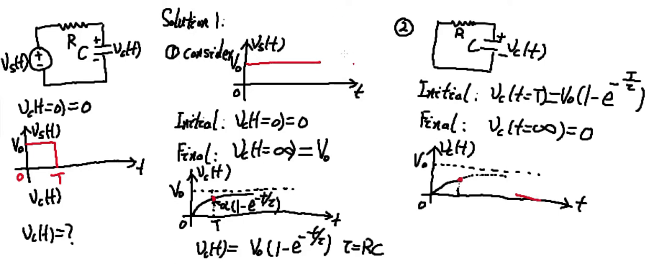So it should satisfy an exponential relationship. It will undergo a decay like this. And we know this trend must be proportional to e to the minus t over tau. But now, since the new starting point is t equal to capital T, it's shifted, so it will be e to the minus (t minus capital T) divided by tau.